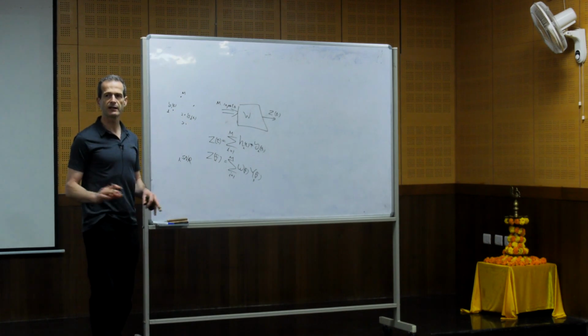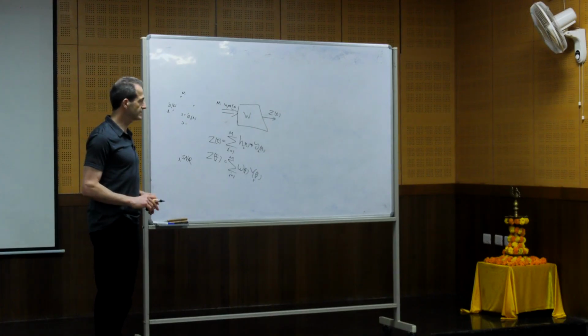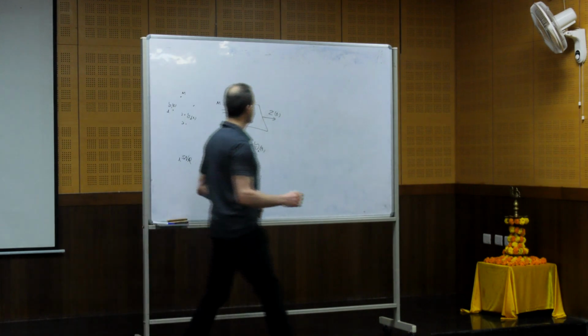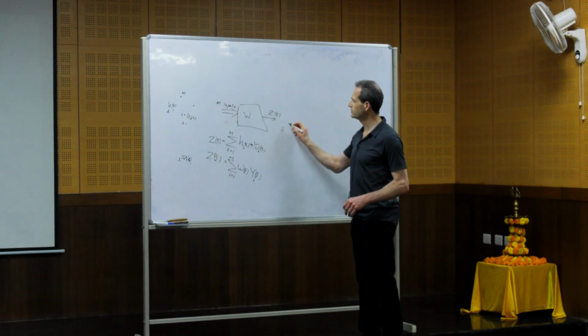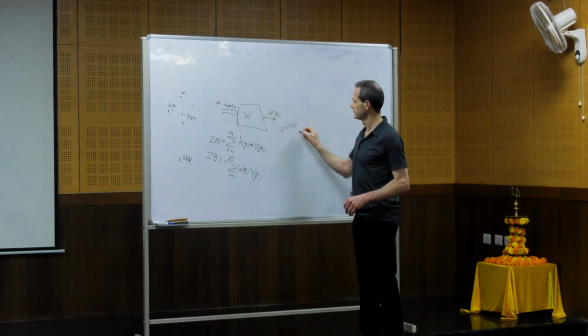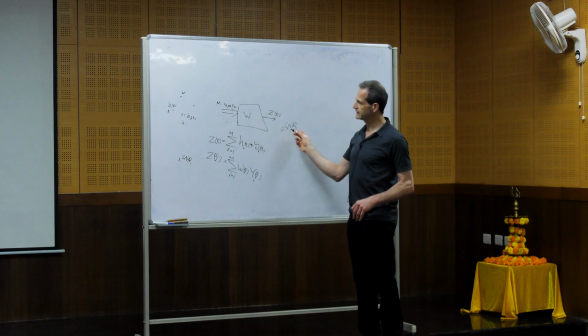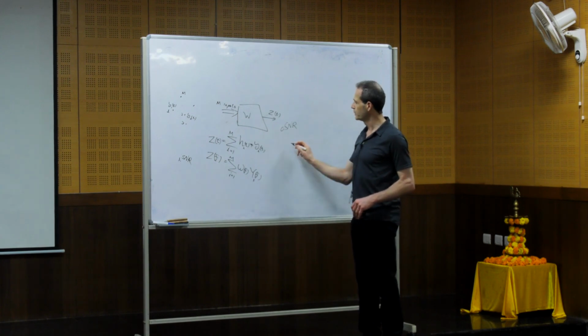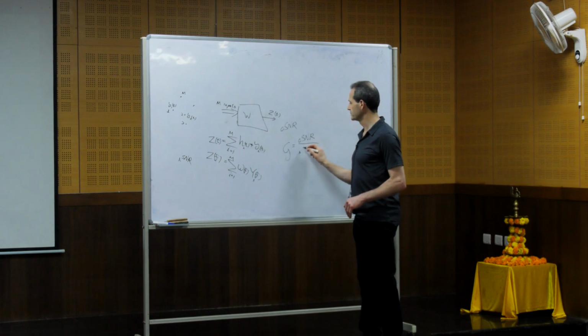Let's assume that the signal-to-noise ratio is the same for all the signals. And we can define the output signal-to-noise ratio. The ratio between output SNR and input SNR we call array gain. So it will be output SNR divided by input SNR.